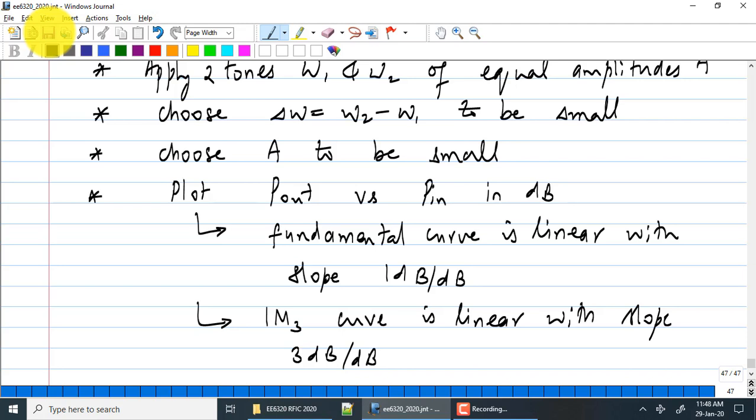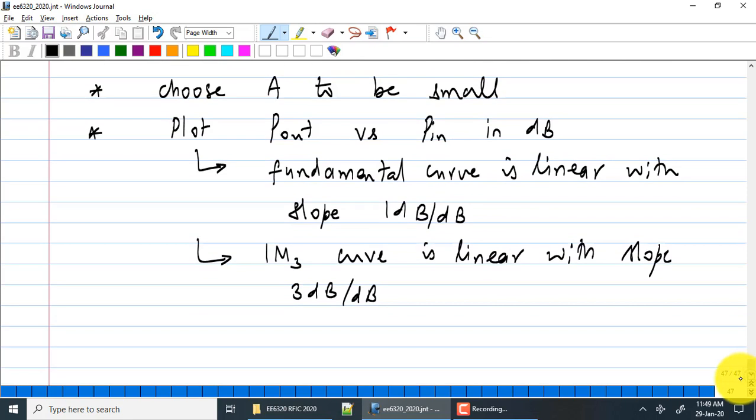Okay. So if you were really measuring in the lab, you would have an estimate of how linear your amplifier is already a priori. You would probably follow this up with a highly linear filter and then pass it into a spectrum analyzer to figure out. Otherwise, your spectrum analyzer may also be linear enough to show it properly, in which case you take the output and monitor only the in-band components. Any other questions? I'm just writing down what we discussed earlier.